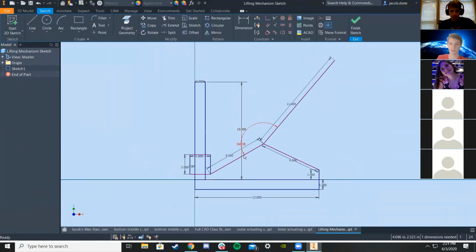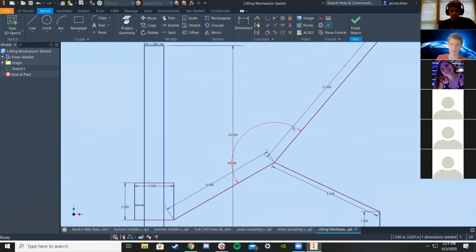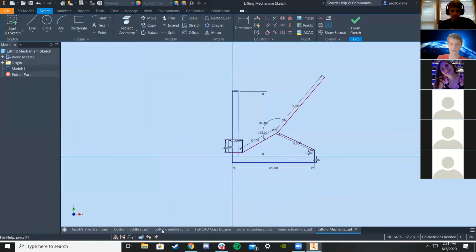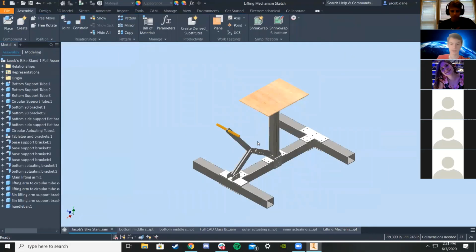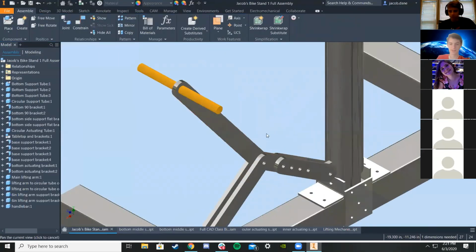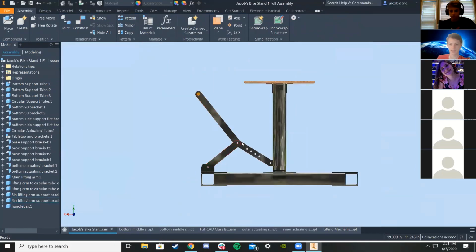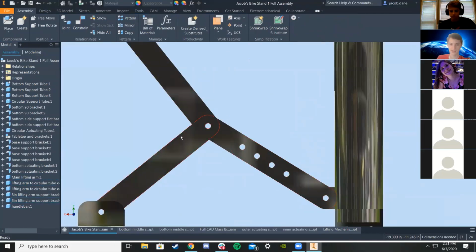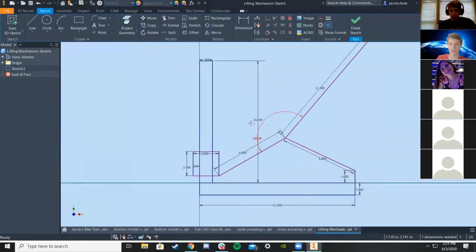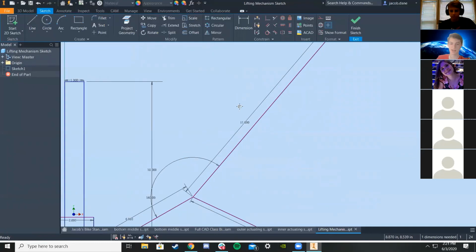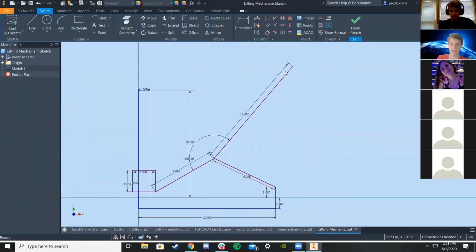So I have this angle constrained to 160 degrees, and the length of this arm is really similar to here. I made this 160 degrees, I made the length of the arm the same, this distance the same, and this distance the same. And so I made a sketch of that mechanism so that now when it's constrained like this, I can pull down here.